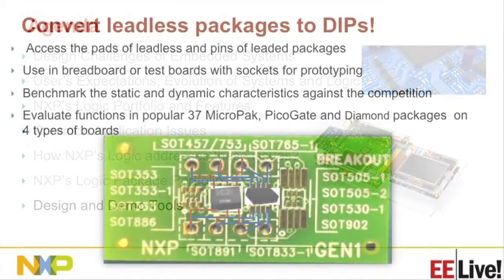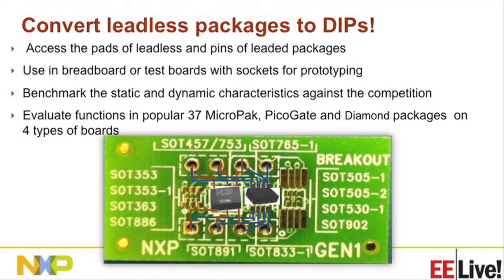So in the final section, we'll look at the design and demo tools. Since these packages are becoming so small, we have some converter boards available. The idea of these converter boards is they will convert the leadless packages into DIP packages, mainly for evaluation and benchmarking, so that you could look at the timing properties, the static and dynamic characteristics of these devices. So only one package can be mounted on the board at one time. So we have the footprints for all these packages, but you can only mount one device at a time. And we have 4 different types which can accommodate up to 37 different packages on the board.